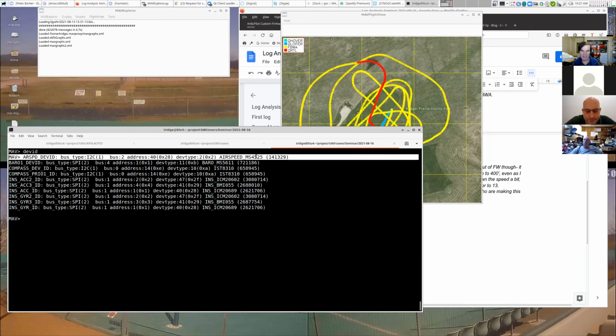Interesting thing about this airspeed sensor, I'll just show you close up on my aircraft what it looks like. If I turn on my light here, can you see that airspeed sensor there? Or am I pointing in the right place? You see the little plastic, that little thing? That's the airspeed sensor, right? It only has one hole in it for the dynamic port, which is the, you know, getting the air ramming in. And the other tube from this MS4525 is just loose in this camera area. It's loose inside the fuselage. So the static is just coming from inside the fuselage rather than having a separate static port.